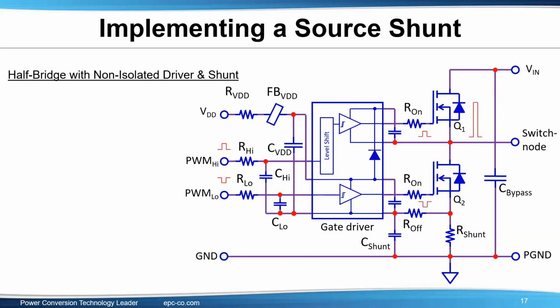How do you determine the power loop inductance? I use Q3D, but they don't consider inductance inside the power device. So I think that's not accurate. What we do is like this. I think there is a nice slide, and that's something you can do, at least on an existing layout. Let me go to the slide, then I can talk. You can do it on an existing layout, and then based on that, you can understand what is going to happen on another layout. I would say it's difficult to predict, but there's one thing.